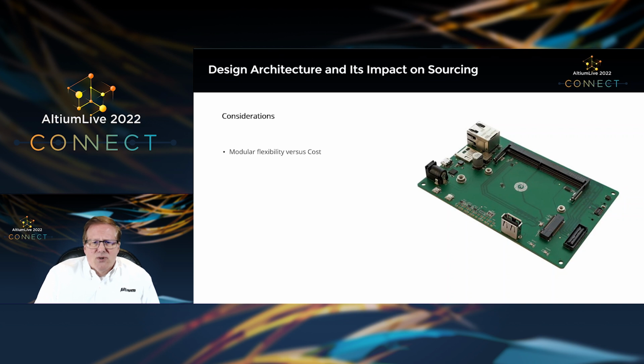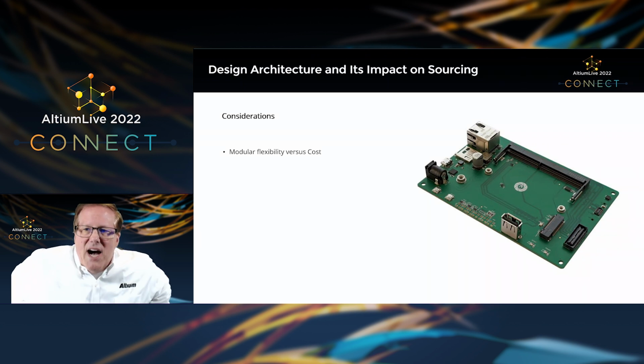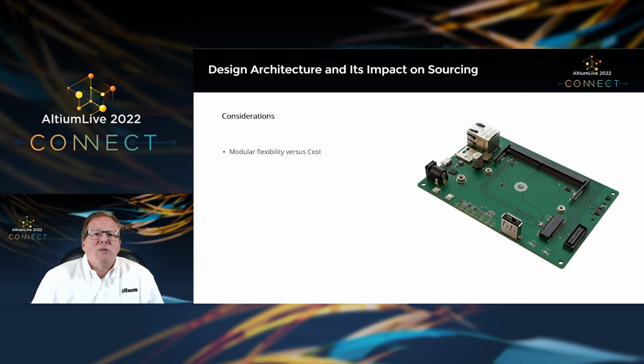There's obviously an additional cost. Those connectors cost. You might not have as much density as far as what you can pack into your enclosure, but it does give you flexibility that can really come in handy, especially in times like we're in now. Say, for instance, if you had a Bluetooth module, and the particular Bluetooth chip you're using is not in stock, very difficult to find. If you had the ability to use, in the same physical module, a different Bluetooth chip, something you could put together real quick, you could mitigate those delays.